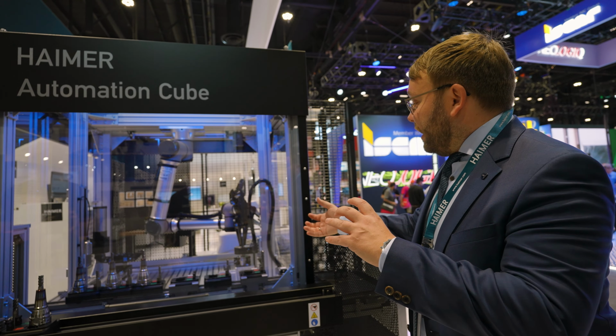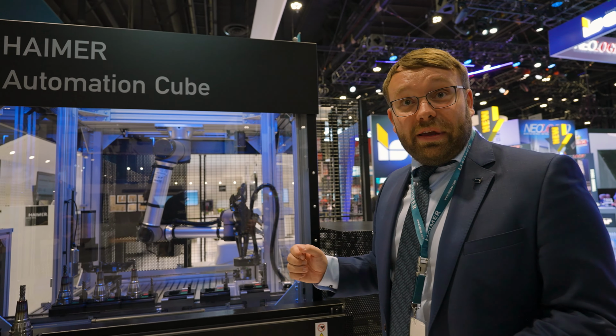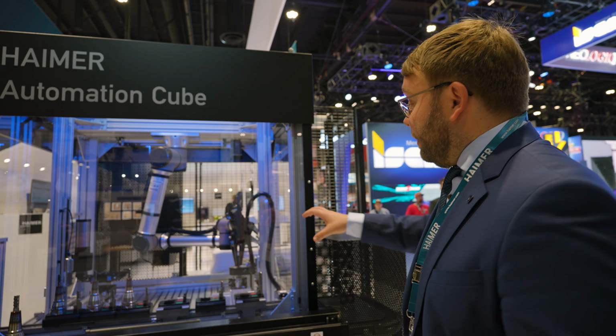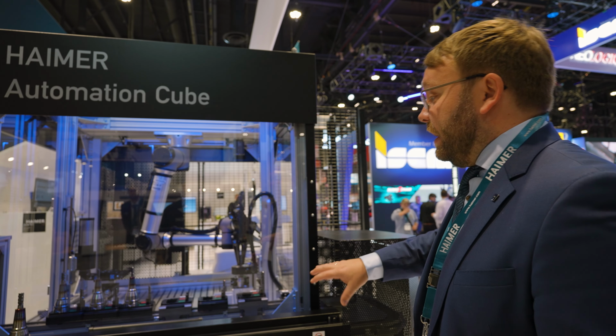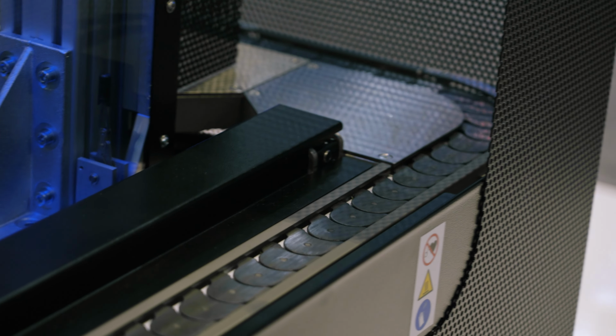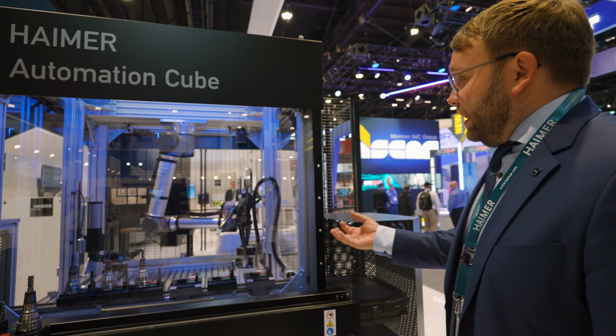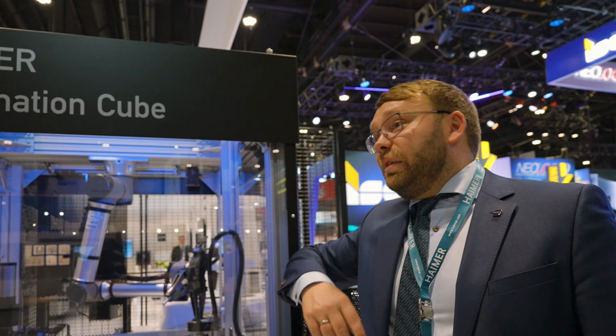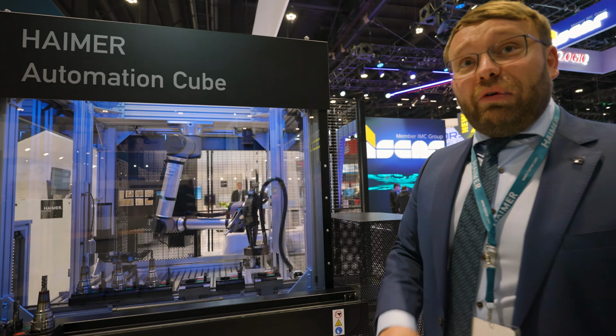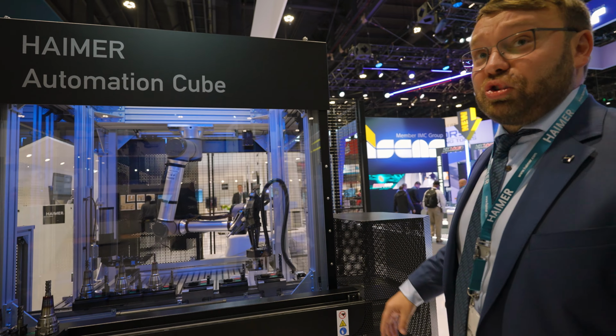This is a cell which combines shrinking and presetting. It could also have balancing added, but in this case it's only shrinking and presetting, and you can extend the conveyor belt if you need more. Now you see it taking out the old cutting tool, putting in the new cutting tool, and moving it to the cooling position, and that's fully automatic. That can run 24 hours fully automatic. You can load it and extend the conveyor belt to have many more tools to shrink in and out.